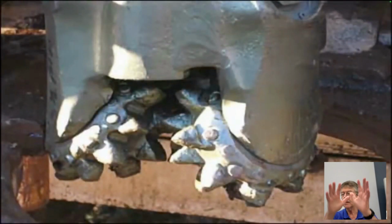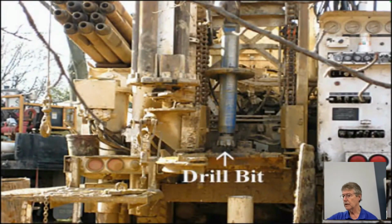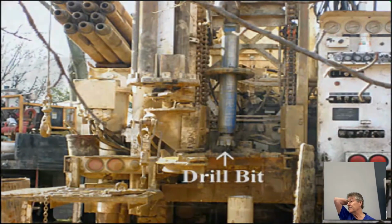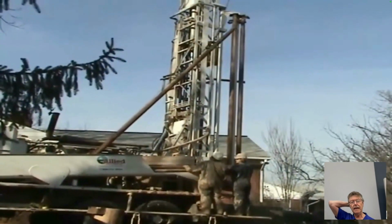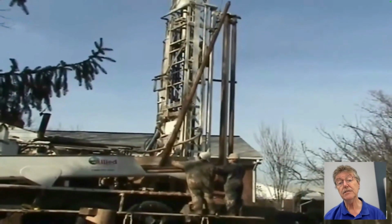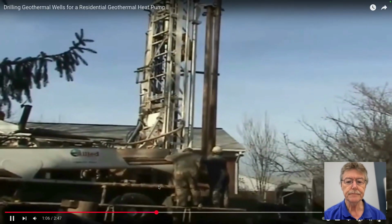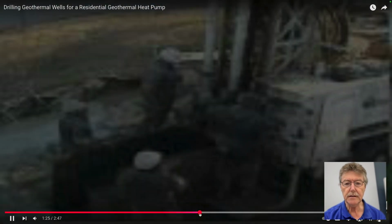Sometimes you get a 300-foot hole drilled very quickly, same way as you do it in a petroleum well, smaller rig, and then put a U-shaped tube in it with a bend in it, send water down, it heats up as it goes down, takes the temperature out of the ground. Groundwater here at 100 feet is probably 55 Fahrenheit, 10 centigrade, and it uses that to offset the heating costs in the house by basically using a refrigerator, phase change in a system. That's exactly what they're doing here.